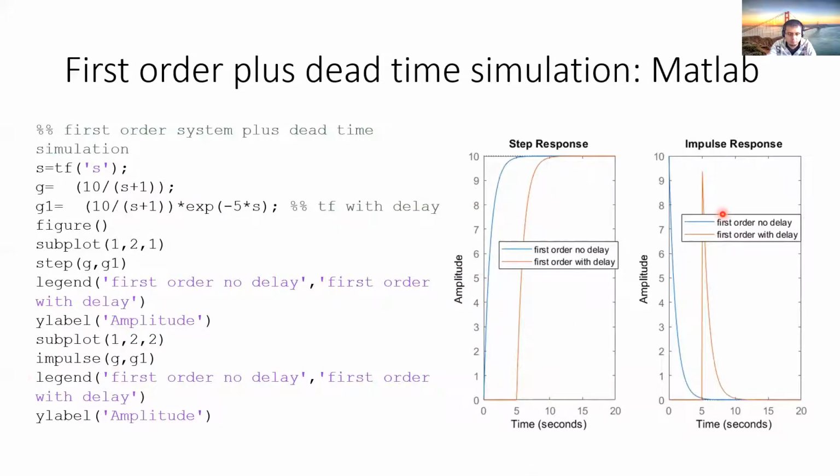But now we can also introduce the impulse response. But how do we calculate the step response and the impulse response for these systems? In that sense, we made a small change regarding the last time. As you can see here on this side, we are using the function step. The function step in Matlab basically calculates the unit step response of the system. If you see here, I put G and G1, both transfer functions.